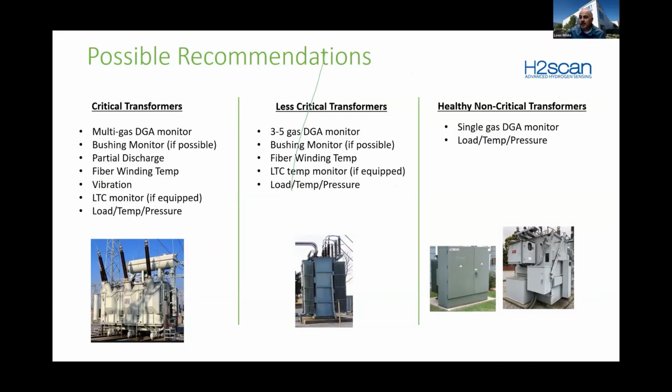And so that can provide a great indication of whether your transformer is designed properly. Is it at 50% load and already overheating, or are you at 100% load and the winding's still very cool? And so you have more capacity in that transformer. Vibration is becoming more and more popular. There are different people coming out with various vibration systems. I'm not too familiar with those yet. I haven't actually worked with one of those personally.